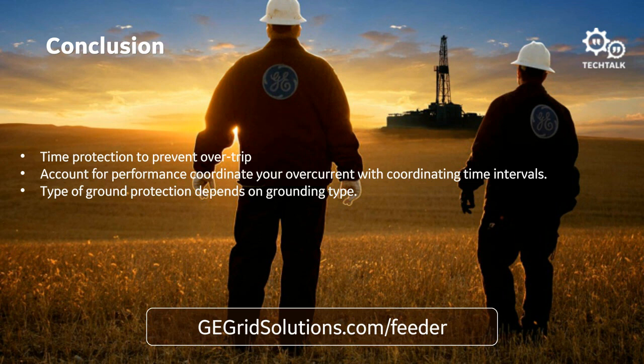The 8 series has a lot more functionality than the 745 that you're replacing, and because of that, you'll see some things flagged or targeted in that report that you might want to look at. A lot of the things just make you aware that those settings weren't in the 745. Some of the things will show up either yellow, green, or red. And the things that are red are things that you really need to look at.